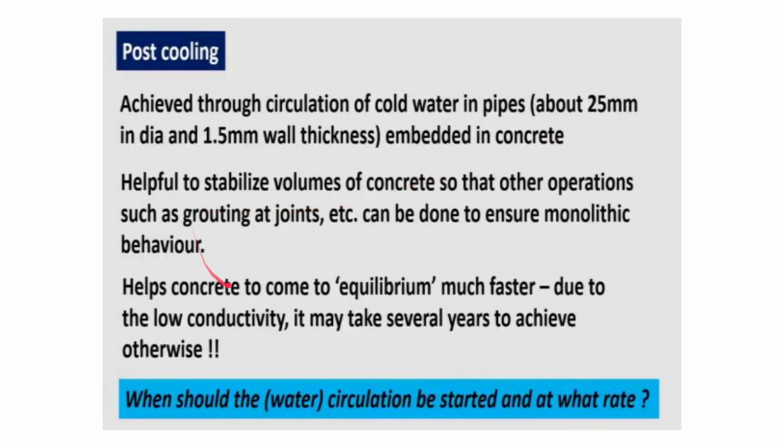They are helpful for stabilizing volumes of concrete so that other operations such as grouting at joints etc. can be done to ensure monolithic behavior. This is important to avoid the cold joints, so there is no segregation of layers of concrete. This helps concrete come to equilibrium much faster. Due to the low conductivity, it may take several years to achieve otherwise.